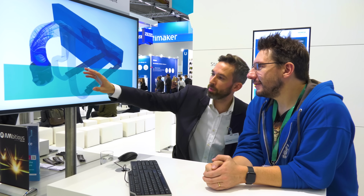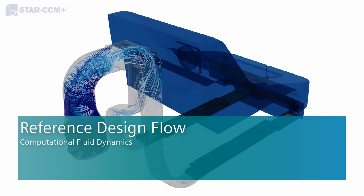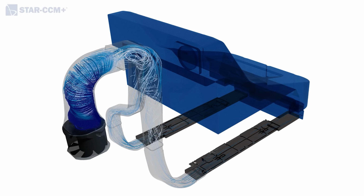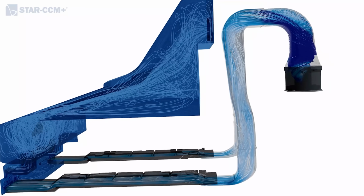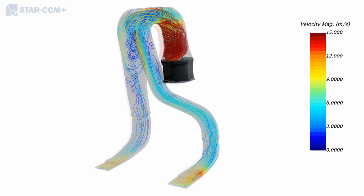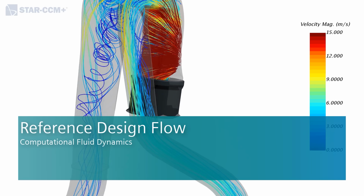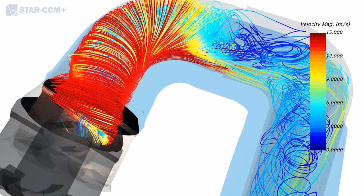So as you could see, we were able to solve this flow for, let's say, the original design, right? And if we look at the details here, it is super turbulent, and turbulence means actually a waste of energy, right? If you generate too much turbulence, then you just waste all the energy that you actually want to use in order to really bring air mass forward. You could see in a little more technical detail here that the velocity is really high in terms of the swirling motion. So, that red means there's a lot of energy being spent in swirling around.